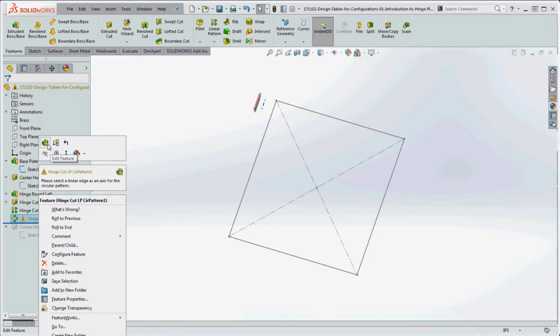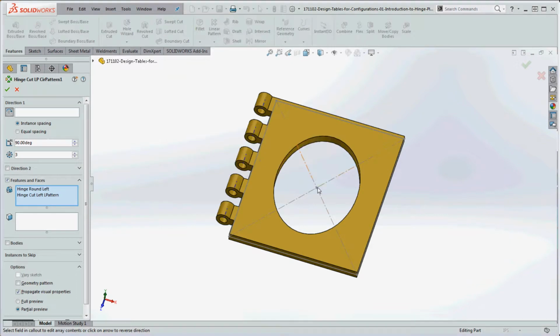So what happened there? What happened is we're trying to revolve around a place where there should be an axis, but not with that ellipse cut in here. There's no axis associated with that, like what we had with the circle when the circle was in here. So we probably don't need that. We're not going to do a circular pattern, because even if we did have an axis in the middle, we could actually make one if we wanted to. We'd take that cut and actually put it in the middle of our feature over here in the middle of the plate, and that's probably not going to work out very well.